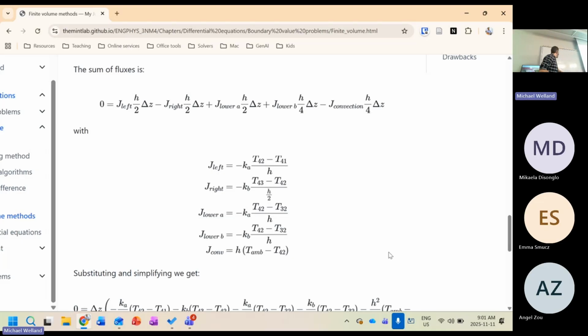What that means is that your boundary condition is having an effect on the temperature gradient inside your material, right? To the point where you could actually say, a priori, whatever your convective heat transport is here, whatever your boundary condition is, you can use it to calculate the slope of the temperature at that point, right?